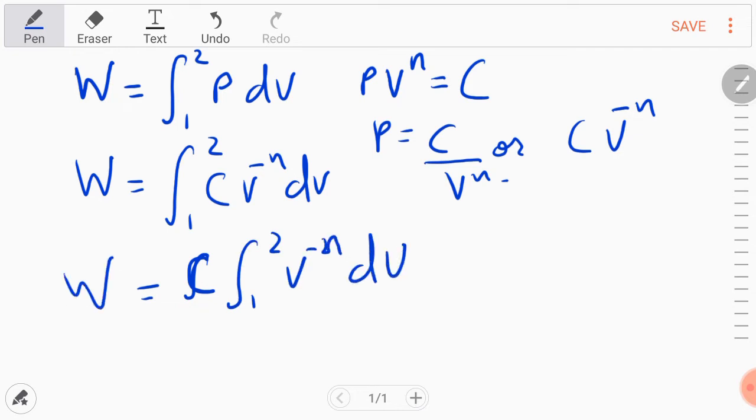In the last numerical, the equation is simpler. It is 1 over V. It is an isothermal process, so it is 1 over V, and the integral of 1 over V is simply log V, and by applying the limits, this is log V2 minus log V1, and then applying the log formula, we have ln V2 upon V1, and we put the initial state conditions.